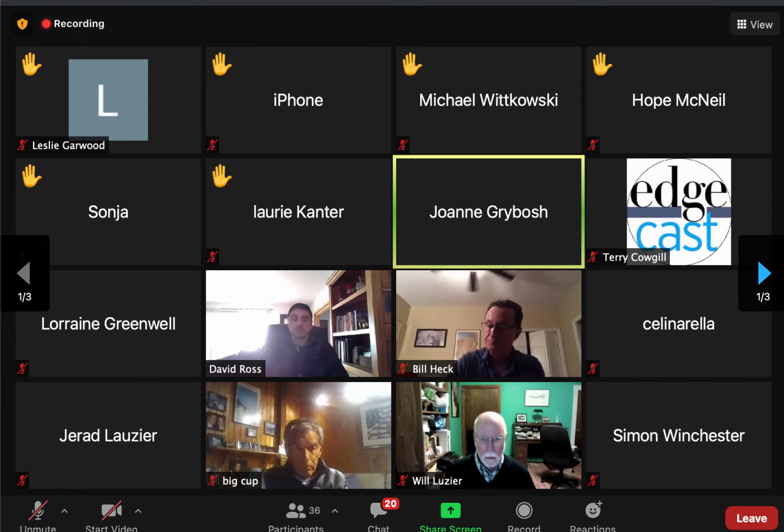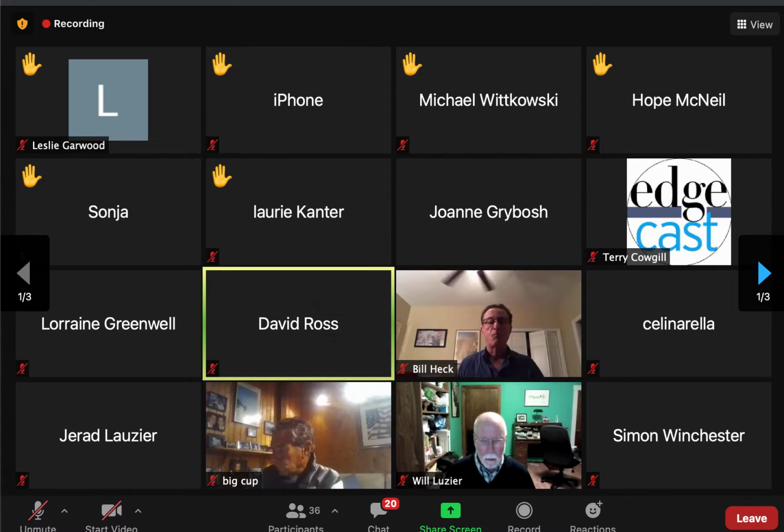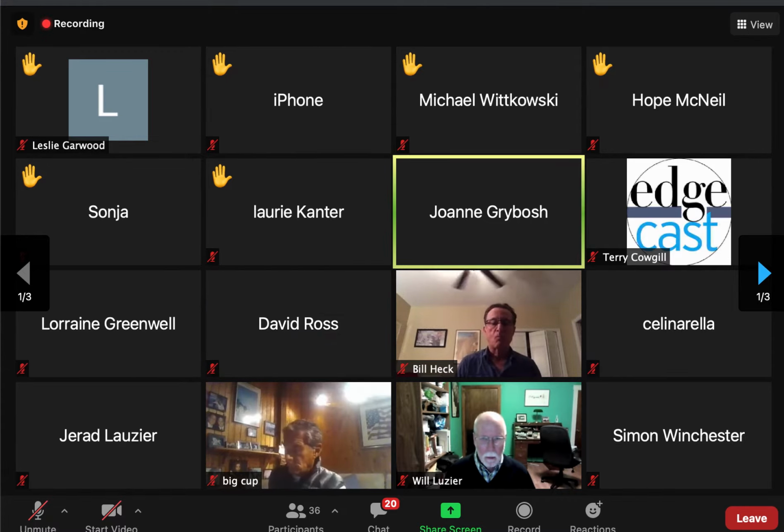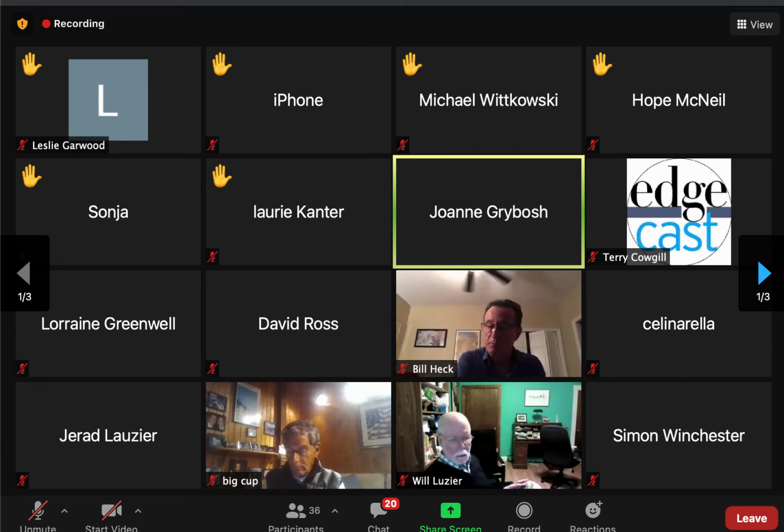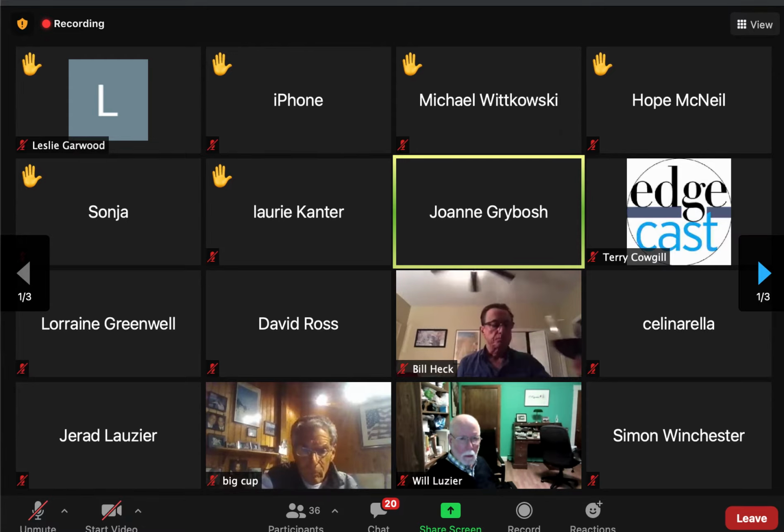As you drive up, Abbey Road is pretty narrow, so there'll be an improvement of Abbey Road post construction. We're going to coordinate that work with the town. It's on town property, so we'll collaborate and participate in that improvement. If you're at the site driveway, you look up. It's about an 8% grade. An 8% grade is like a wheelchair ramp. And then you'll come to a 4%, or half of that, parking area. So you're going to have a ramp up, just like a wheelchair ramp, and then a flat parking area. Keep going past. There's a retaining wall. Yeah, there's a 5-foot retaining wall.